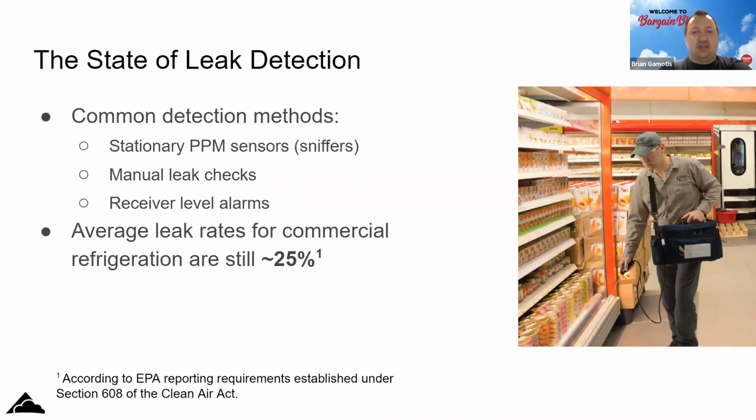The mechanical sensors are prone to damage from being bumped and things like that. You'll get a decent number of false alarms from them being bumped or just getting hit, and they just quit working. Those ones tend to be a little more sensitive as well to various kinds of floor cleaners in the walk-ins and things like that. So you'll get some false alarms that way.